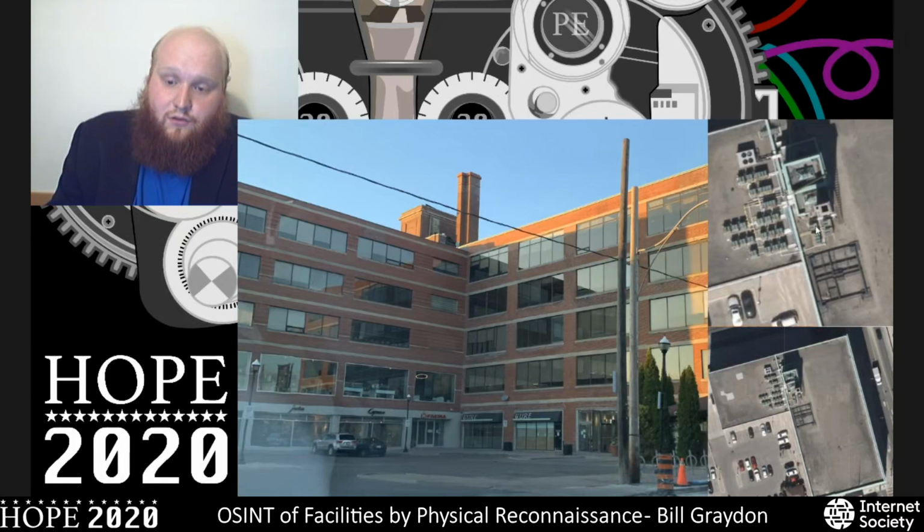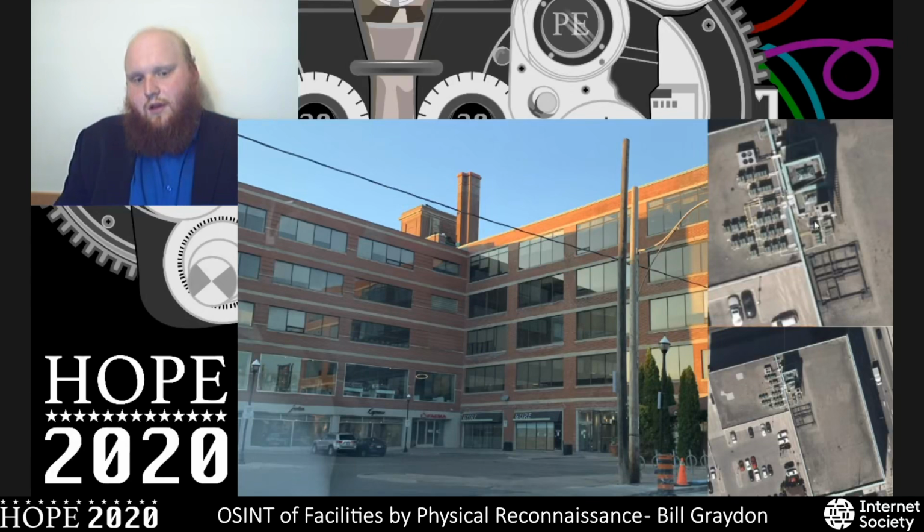Very, very interesting to note as well is this structure here. So this used to hold some sort of heavy HVAC equipment. We don't know what, but we do know that it is supported right above the structural columns of this building. And it's not visible in the pictures here, but those structural columns actually line up with the breaks in the fenestration. So from that, we can infer that there's 4 columns here, that they are likely matching up with the breaks in the fenestration along the building, which makes sense, and columns tend to be in a consistent grid throughout. So we can deduce the entire structural diagram of this building by these 2 pictures.